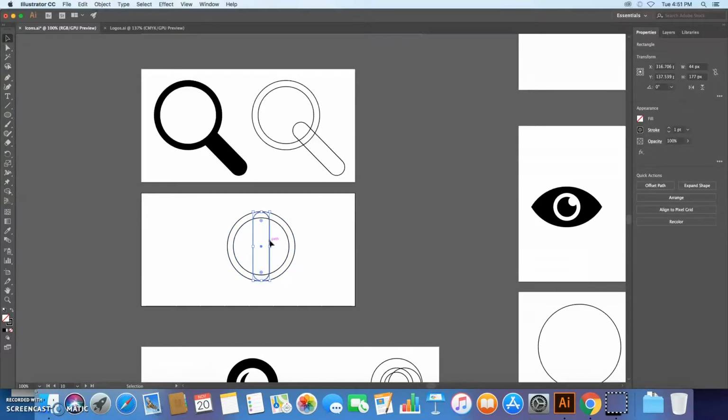And to move this straight down, there's 2 ways you can do it. You can either click and drag and just hold on to those smart guides that pop up, or hold Shift on your keyboard, and that will make sure that you can't get off of moving straight down or straight to the side. Or the other way that you can do that is use the keyboard arrows to just move up or down. And you can use Shift to move in larger increments with that instead of having to hit it 100 times.